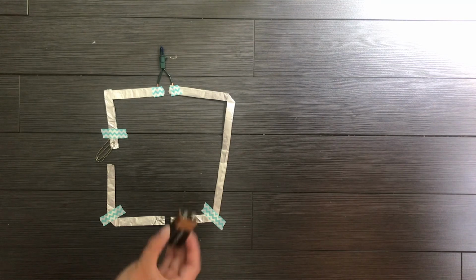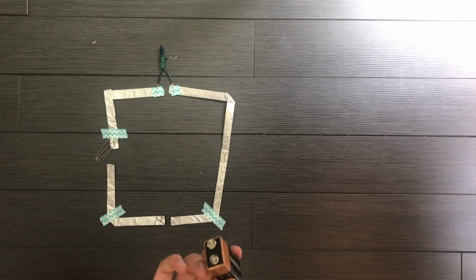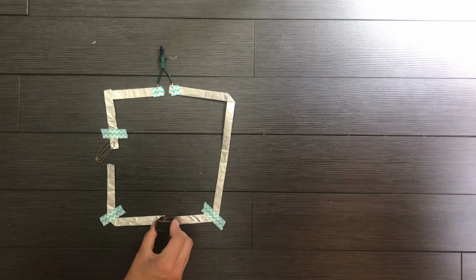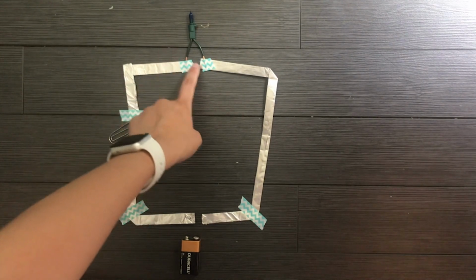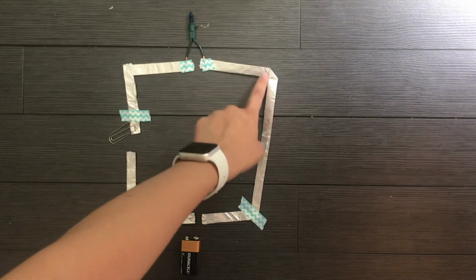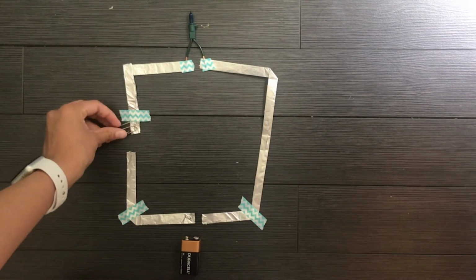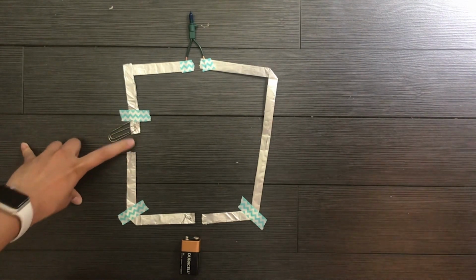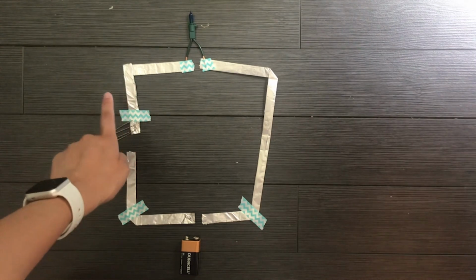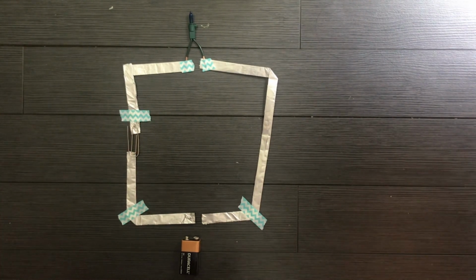So when I take this 9-volt battery and close the circuit, what do we think will happen? Let's see. Nothing. So why did nothing happen? Let's start at one side of our circuit. So we go all the way through, and we see this. Our switch is open right now. That means we have an open circuit. So when the electrons come to this little gap, they can't flow across to the other side. So when we close the circuit, let's try it again.